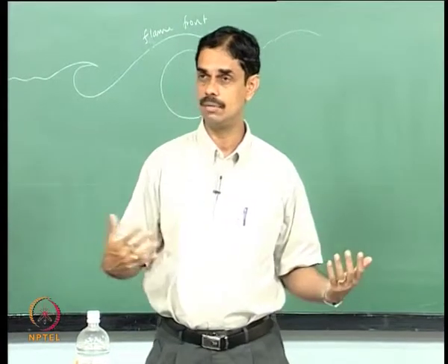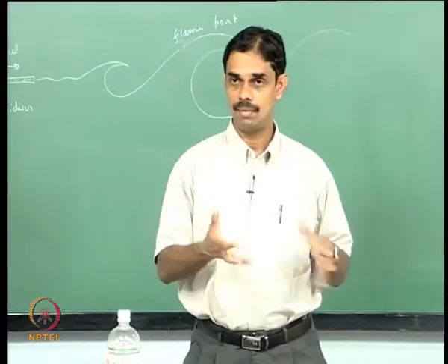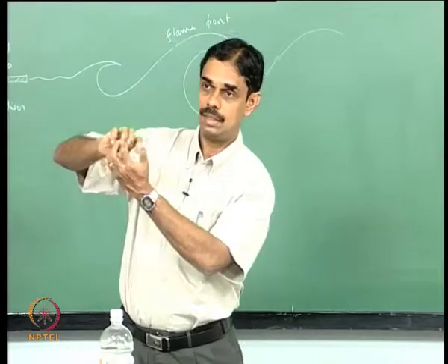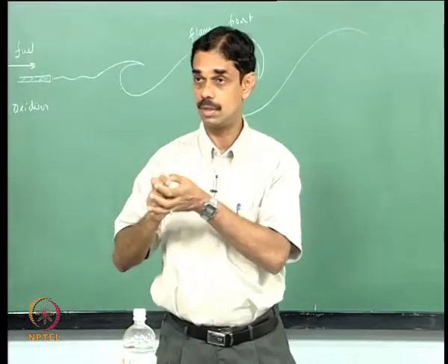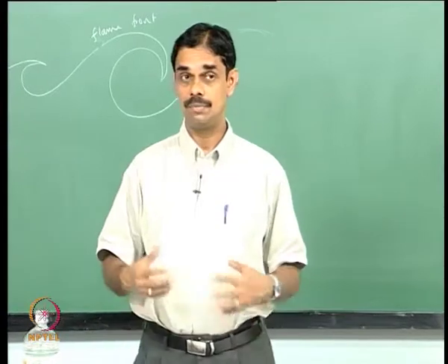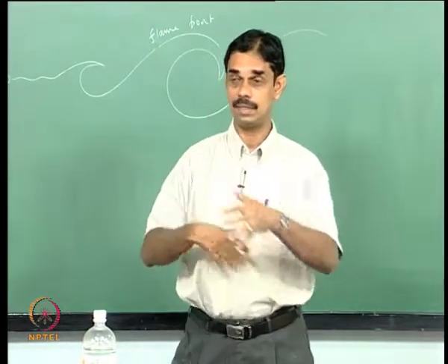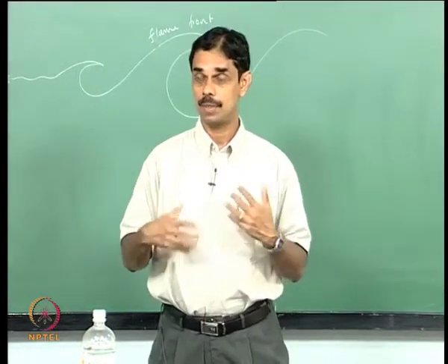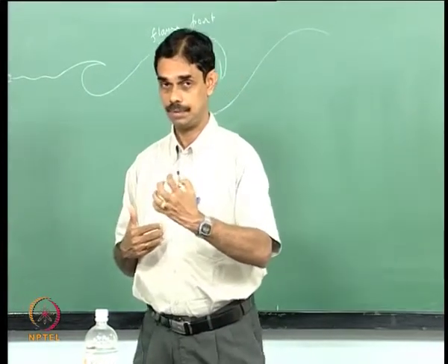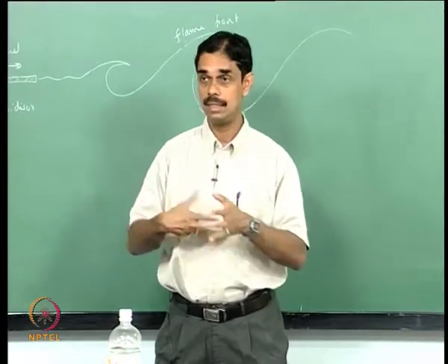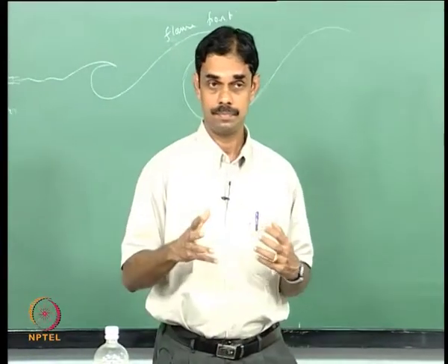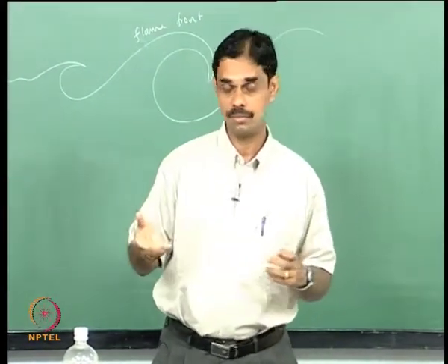So you are not having a continuous burning in this kind of situation, but you have the mixture that is going to burn get entwined into the vortex, and when they are mixed at a molecular level, bang, it burns. Okay, is this concept clear? If you are talking about a diffusion flame, you have fuel and air mixing from either side, but if you are having a premixed flame, you may have reactants on one side and hot products on the other, and the hot products, which have the hot radicals, have to mix well with the cold reactants, only then the burning will happen. This is a premixed flame, right? In either case this scenario would work.